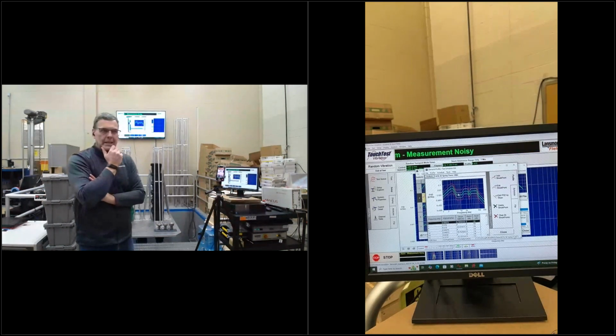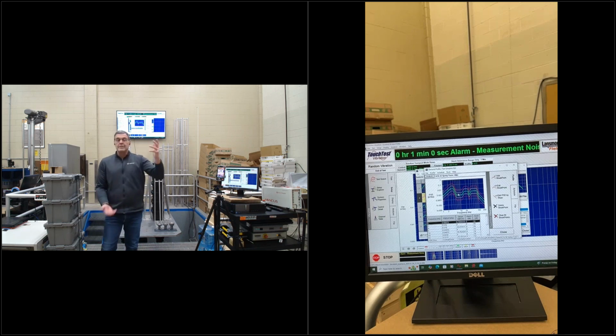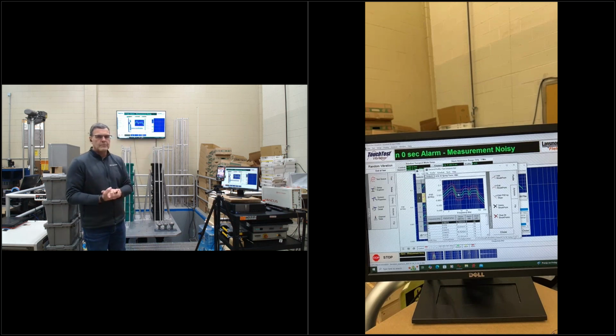It was more to understand the amplification. Meaning if I have an instrument here on the table, let's just say this is the floor of a truck bed or an intermodal container, I want to know what's the input vibration. Then I want to know, if I have a sensor on the bottom pallet, what's the response of that pallet to the input. And then if I have another pallet up here with another load, I have another instrument to say what's the input, response number one, response number two. So I can understand the transmissibility, or the amplification or attenuation, that occurs when shipping through that environment.